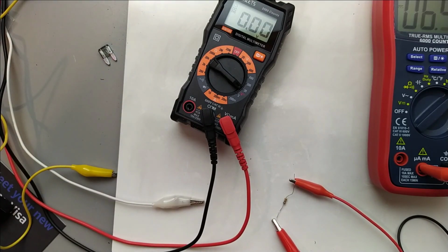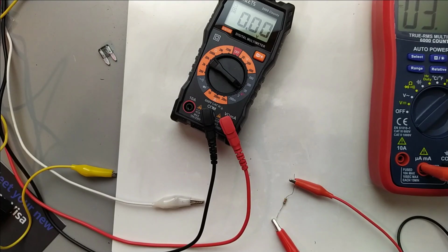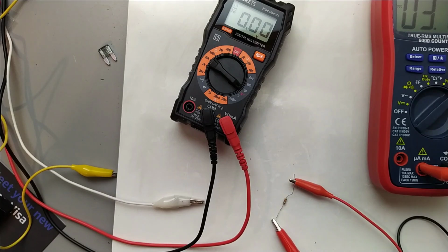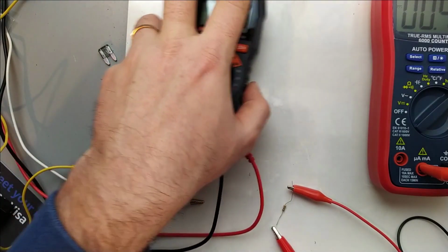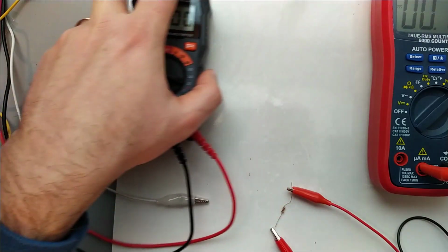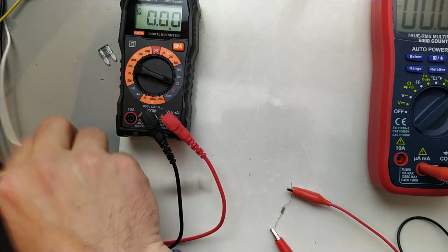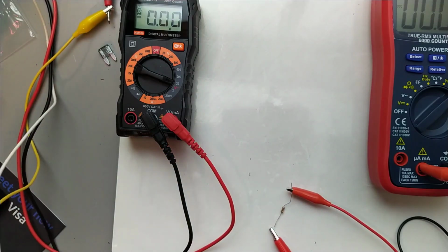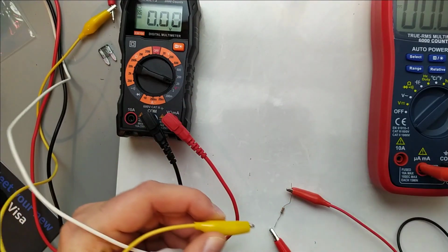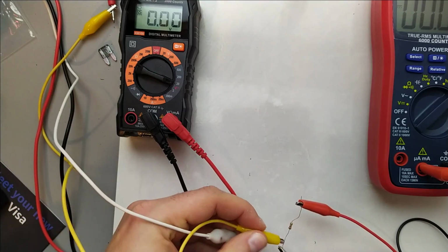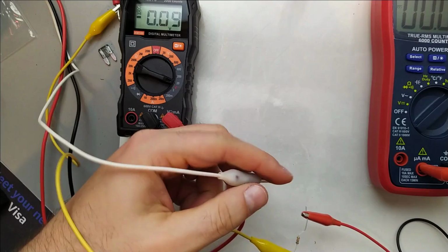So let us now run some current. You see when I change the voltage at the power supply, we have some current flowing through the resistor, and it is measured by the ammeter. So that's good. Now, in order to get current voltage characteristic, we need to connect also a voltmeter in parallel.